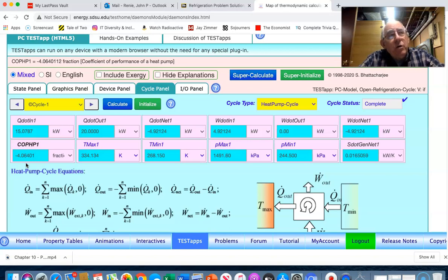It was 3.06. And that makes sense because the difference between the two heat transfers is always the amount of the work. And so when we have, as part of our heat transfer, we add the work of the compressor, since we're dividing by the work of the compressor, the COP for a heat pump is always going to be 1 unit greater than the COP of the same system for a refrigerator.